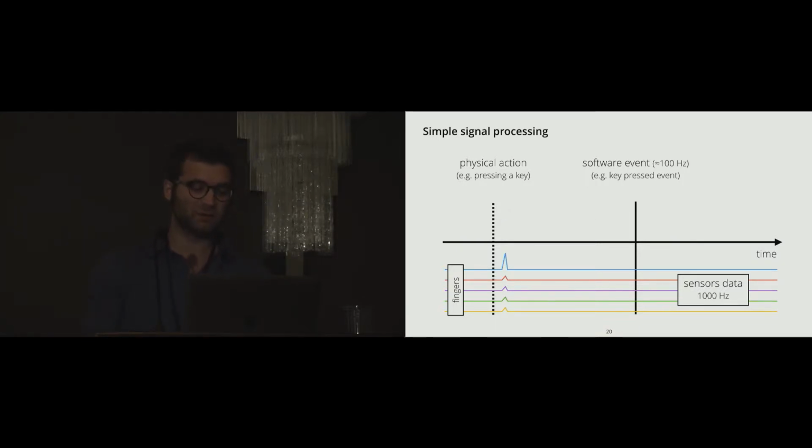If a second contact occurs with its time window overlapping the first one, the two time windows are merged into a unique one, and the algorithm retrieves the two max values. Those contacts, which are less than 30 milliseconds apart, are considered simultaneous by the host application, and thus fingers need to be disambiguated using a heuristic, like the XY position on a touchscreen or the key location on a keyboard. To be noted, finger identification is available at most at the second touch frame.